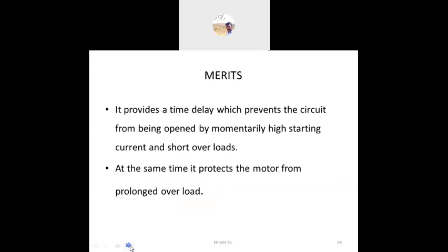Some of the merits of thermal relays: they provide a time delay, which prevents the circuit from being opened by a momentarily high starting current or a short one. So it will not open instantly; it will take some time.